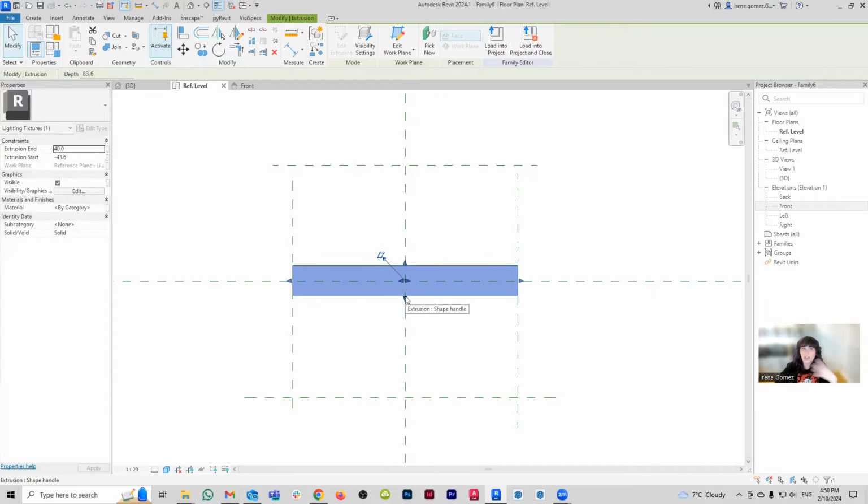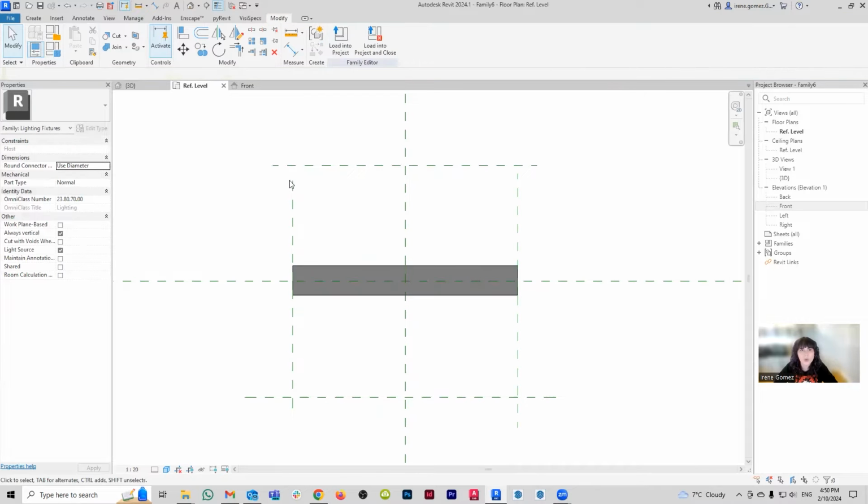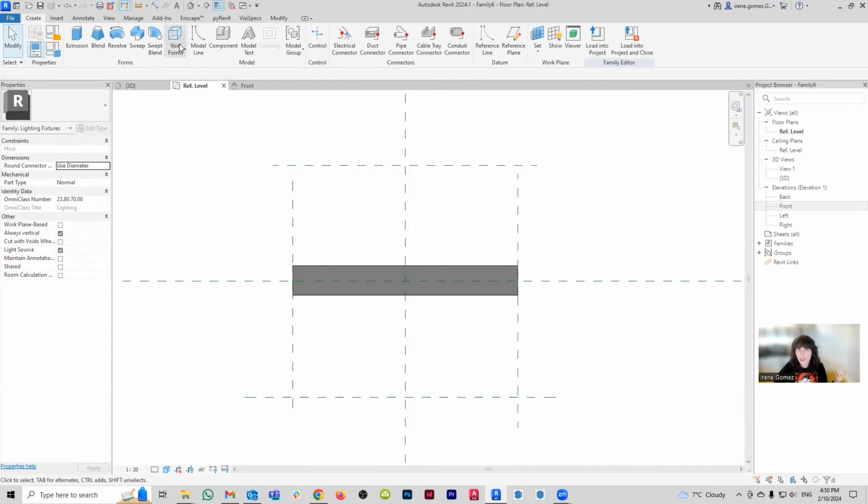Again, because this is an organic shape, I'm not super concerned with precision. For example, you can use these numbers to be super precise, but you don't have to. So let's say, sure, let's leave it there. So what I'm going to do now, from the top view, is use the void tool to stamp the shape of the petal out of these extrusions. So again, you can think about it like you're just cutting a cookie.